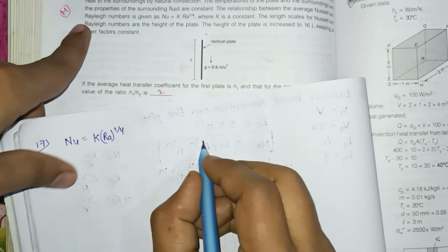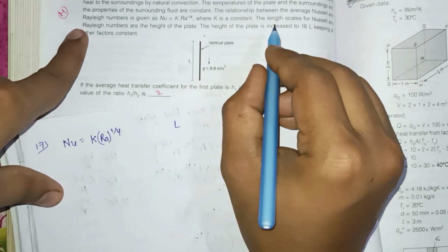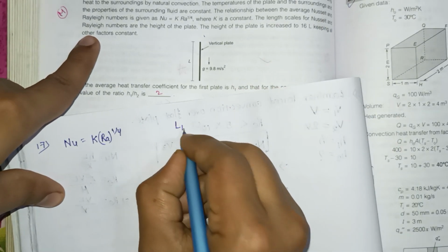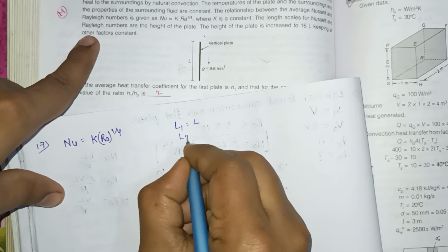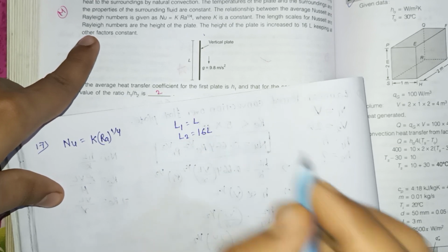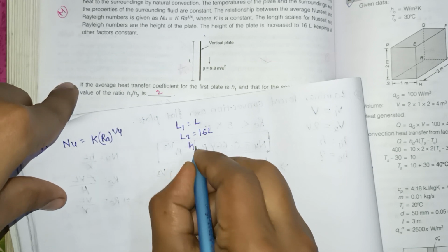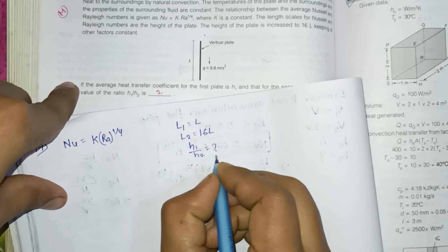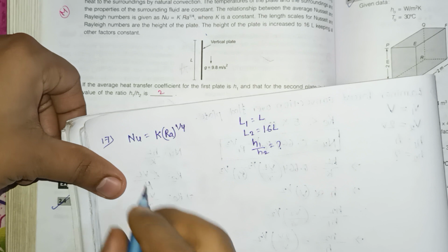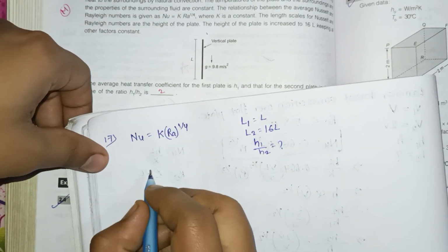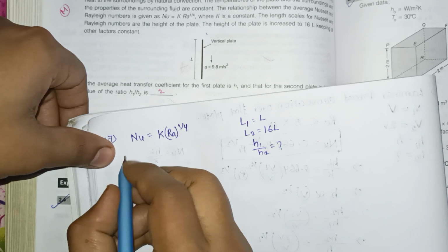And what else is given in this question? The length scale for the Nusselt number: the initial length L1 is equal to L and L2 is 16L. You have to find out the value of H1 by H2. So Nusselt number equals K into Rayleigh number to the power 1 by 4, and we know that Nusselt number